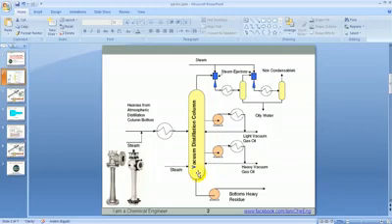After a point, heating the crude under atmospheric conditions would result in thermal cracking, which means a catastrophe for a distillation column, which means that plates would be clogged by coke. Here vacuum distillation comes in handy. Vacuum distillation tower rule: whenever you reduce the pressure, the crude boiling point decreases, and hence you can enhance separation without cracking. That's the main point of the vacuum distillation tower. If you heated the crude, you could get thermal cracking in your tower.